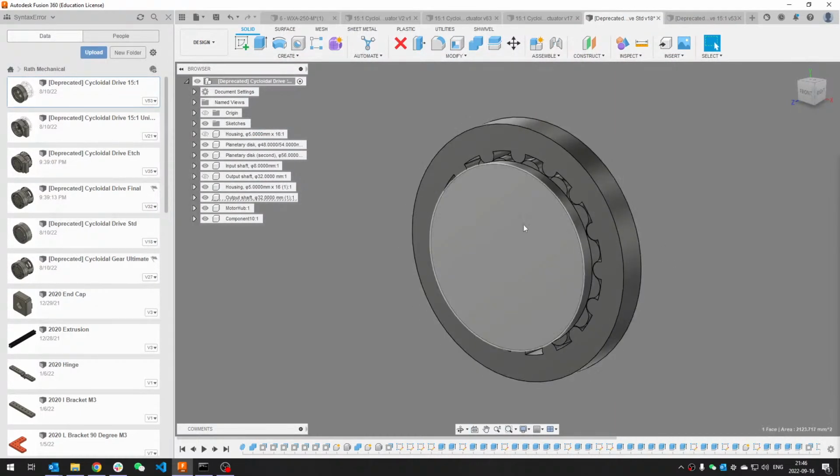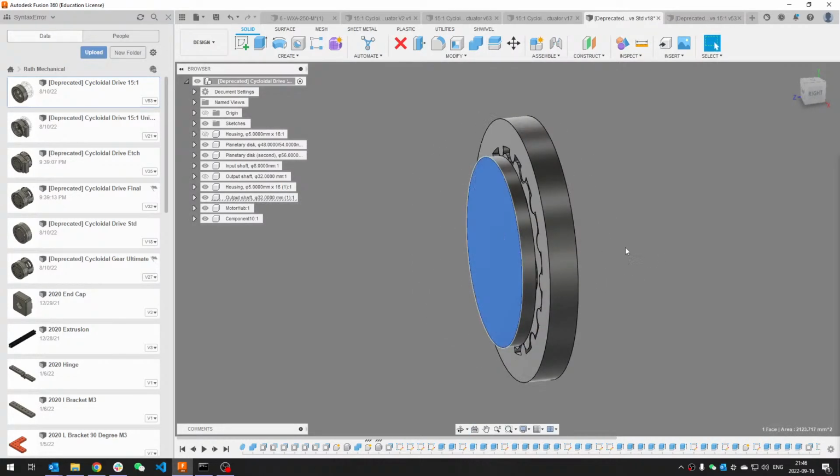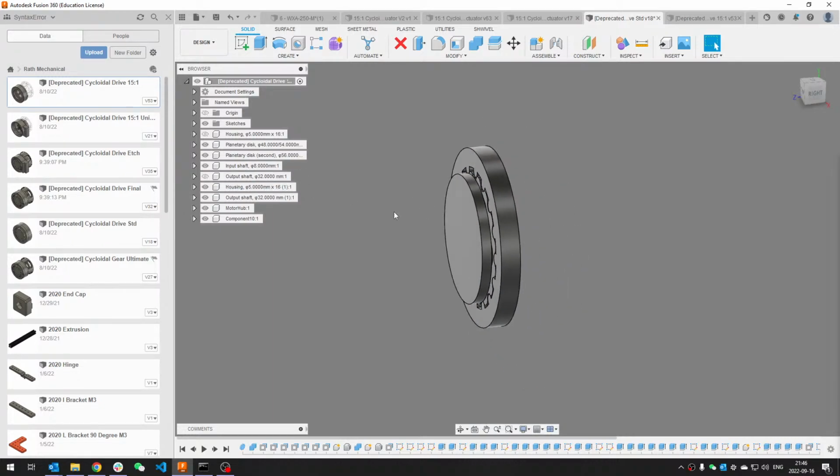In the other one, we attach the output shaft to the motor housing, and it's the housing that rotates, and it's the output end. This will be very useful for connecting, for example, at the elbow position, where you have two rods joining together and you don't want something sticking out in front to drive parts.